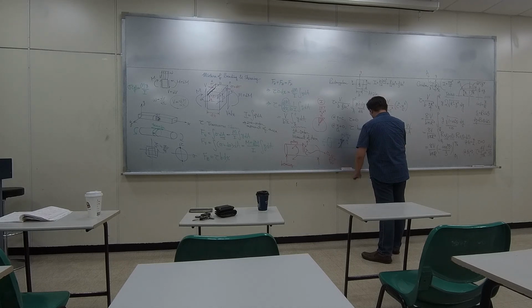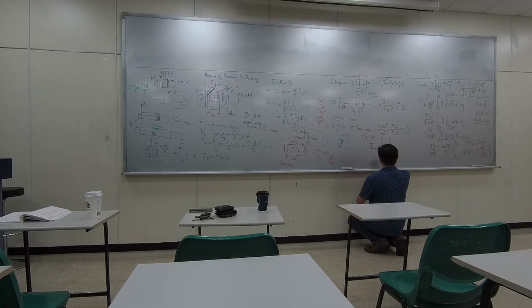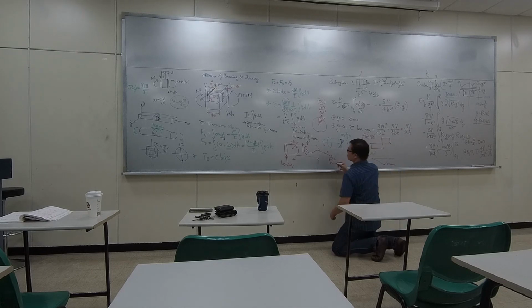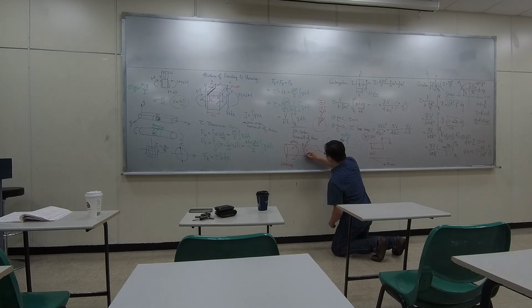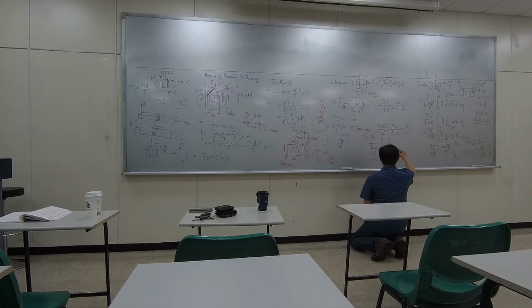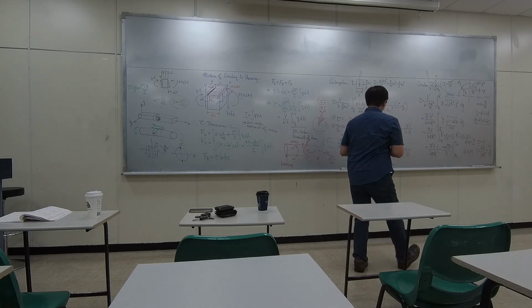I remember the shear looks like this, and the moment looks like it's negative, so it looks like this. This was the moment, okay? So we said this point has the maximum bending moment, so we know somewhere over here we do have normal stress of M radius r over I. So this is the second thing that we need to deal with.